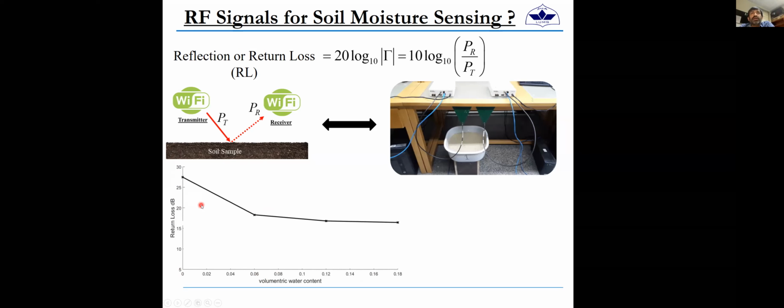So now what does this show? This shows me that this is my model in the given settings for measuring soil moisture content of a given soil sample. कैसे? So in the given setting, someone comes with unknown volumetric water content, और वो आपको कहता है कि अच्छा मुझे बताएं इसमें soil moisture क्या है. So what will you do? You put that soil sample here. You will run your experiment. You will get a value of return loss. For example, you will get 20.